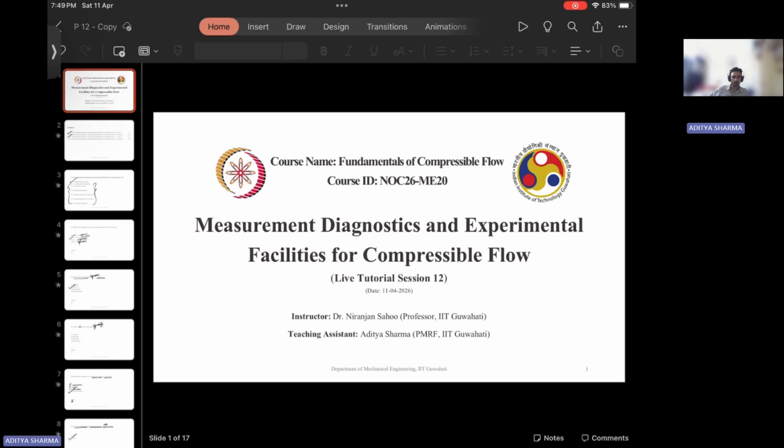So this was your first lecture. Then there were shock tubes, which again are used to study supersonic flows, right? Where we have a driver section and a driven section separated by a diaphragm. We pressurize the driver section, the diaphragm bursts, we get a shock, right? So this was there.